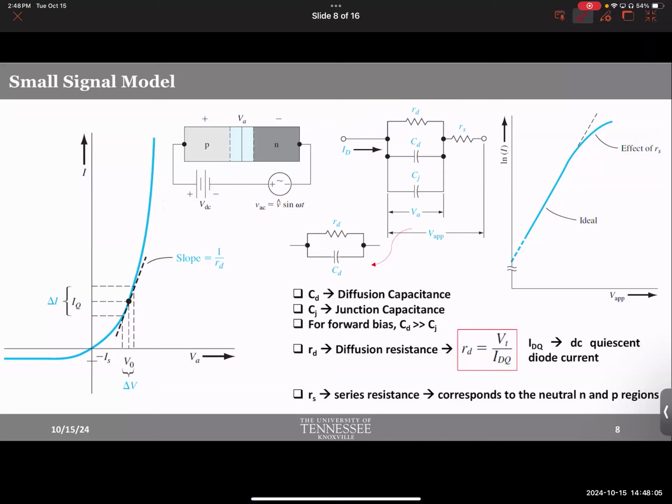So imagine, here is a principle. If there is some sort of hindrance for electrons to flow or holes to flow, we represent that with some sort of resistance. Isn't that logical? If there is some sort of lag or a delay between something getting charged up and charged down, we represent that with capacitance, as you can imagine, right? So similarly, you don't see a lot of inductors here because these devices typically don't have much inductance to deal with.